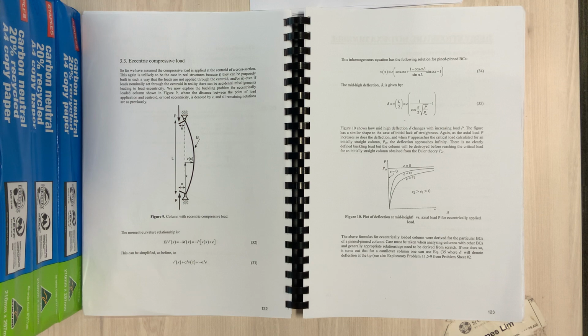There are residual stresses, particularly in steel sections when they're loaded. These residual stresses arise during the cooling process of the steel. So when you get your molten ingot and you turn that into your steel section, you're going to be trapping in some stresses, and these stresses can be almost as high as the yield stress. And of course the residual stresses are not the same in both directions.